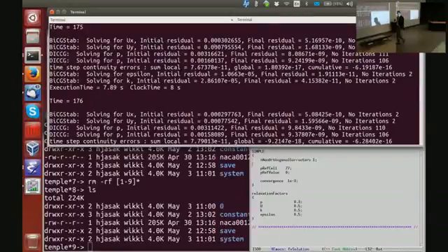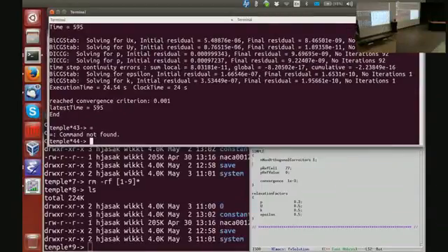By now this should have converged. And you can see here it says reached the convergence criterion 10 to the minus 3 in 595 iterations, which means that the biggest number of 5 times 10 to the minus 6 and so on is less than 1 times 10 to the minus 3, and that says your solver has converged. In many cases, you will see the pressure being the last variable to converge, which is quite typical for the segregated algorithms.